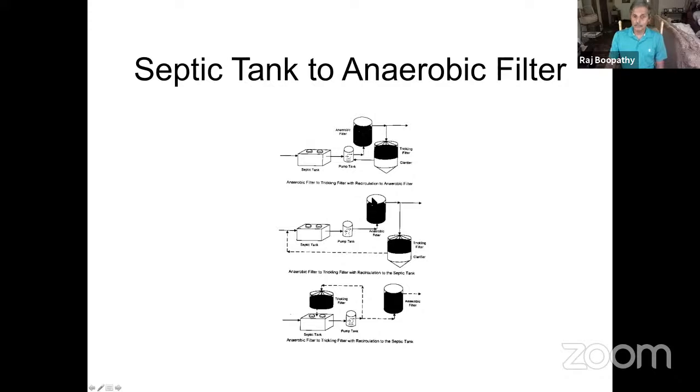And then we have the household type. If you live in a rural community in the US, you have the septic tank, and the septic tank could be treated in an anaerobic filter. It's the same type of filter that you put different rock or ceramic or bead filters in, and the wastewater goes through this filter before you let it out into the receiving body, because we have some strict regulations. So in the US, the septic tank collects into the community, and they don't have a big wastewater flow. It's a rural community, and they'll have the anaerobic filter set up for, say, 100 households. This wastewater goes in there, and then after it's treated, people monitor the COD and solids, and they let it out.